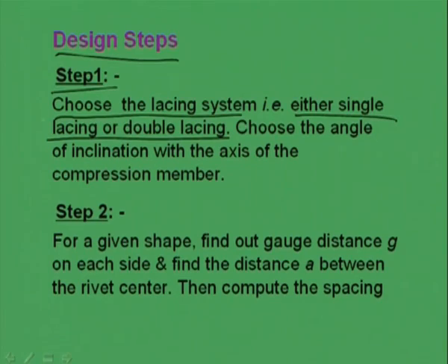So, first step will be to choose the lacing system, whether single or double lacing, and then choose the angle of inclination with the axis of the compression member.